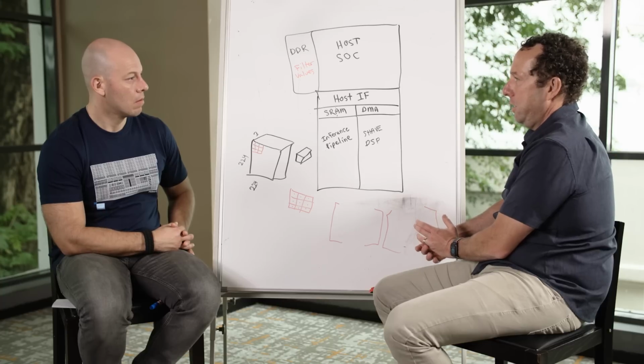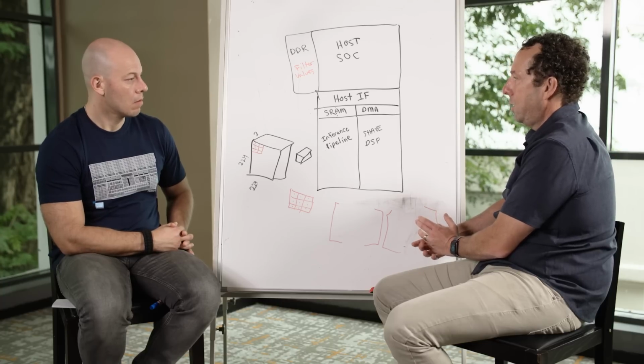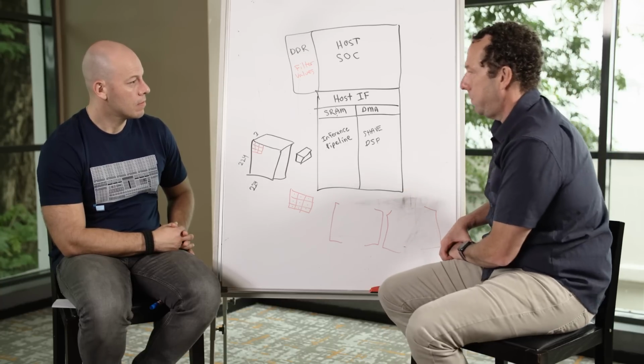The key things for neural network execution and neural network power are really how many times you read and write data, and then also how efficient your matrix multiplication is. So through this, we can get a lot of data reuse. We have internal register files inside our MAC array where we can get a lot of data reuse that can help reduce the power consumption.